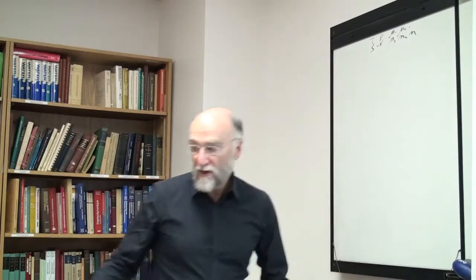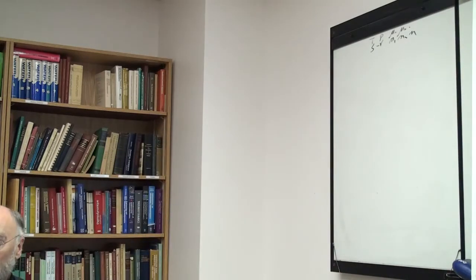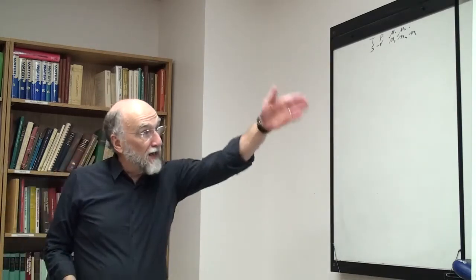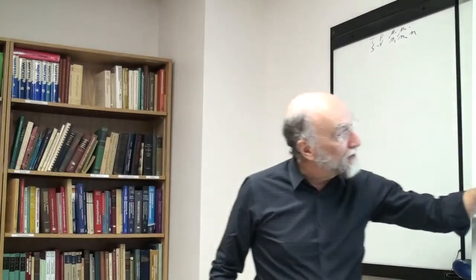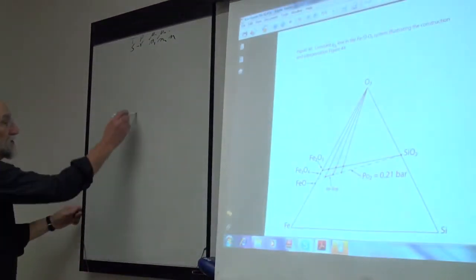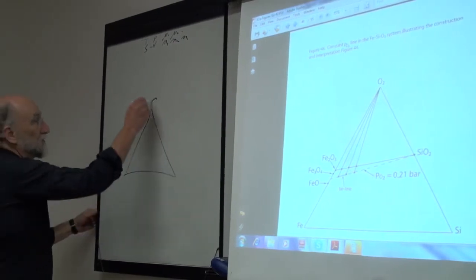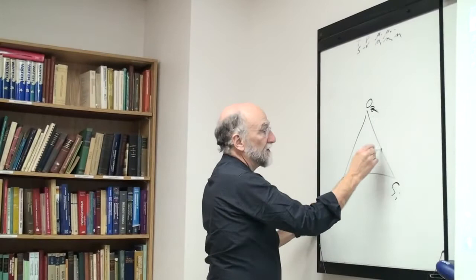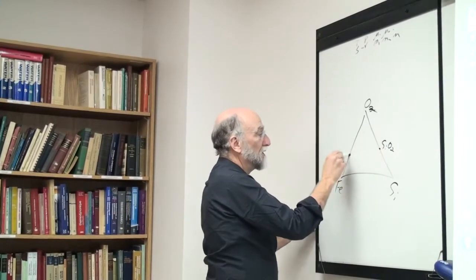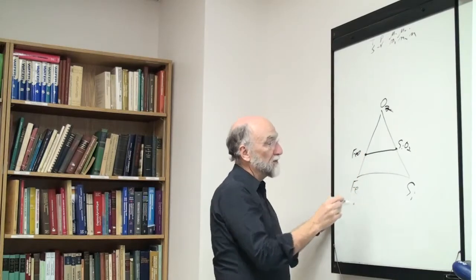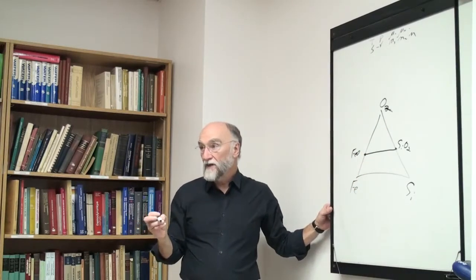What I just showed you here is you could consider that you have it in equilibrium with, okay, so this is what happens if you fix the oxygen pressure. Geometrically, you're tracing along this line and projecting it onto that line. You could consider what you're doing now is you've got oxygen, Fe and silicon. Over here I have SiO2. Here I have FeO. And what I'm doing is I'm taking a line of constant iron activity.